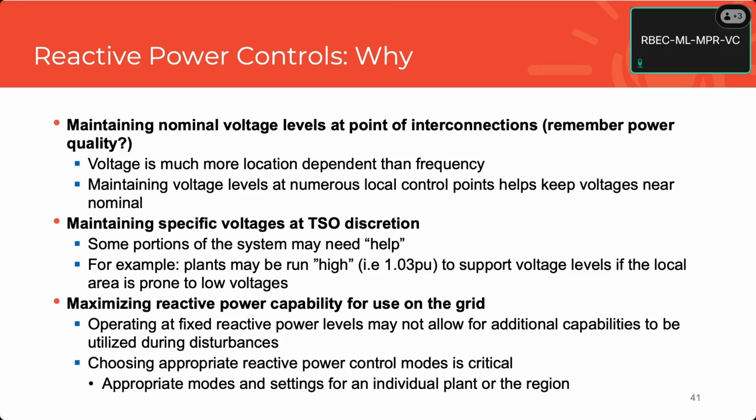Yeah, and the nice thing about droop for commissioning plants or measuring plants when you're in the field is that it's a very measurable thing. You can just look at the Q or look at the active power and measure the frequency or measure the voltage. And then it's a simple calculation. So in steady state, you can measure what the droop is. So that's a very nice data point for validation.